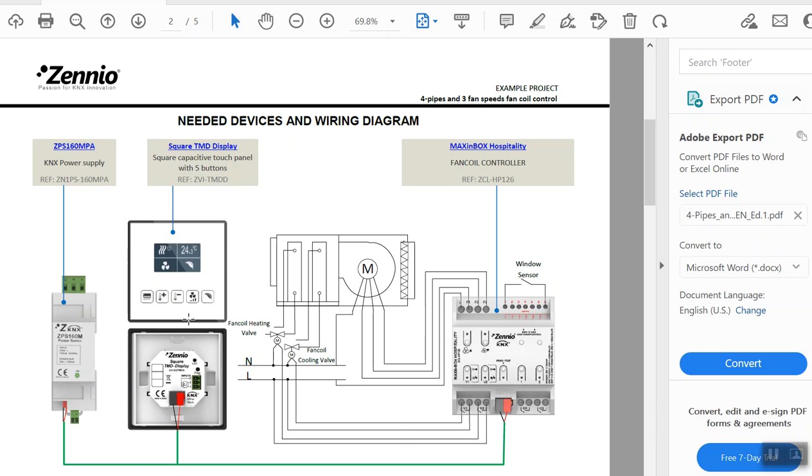In the thermostat you can see the pictures here. This is the on-off for air conditioning or fan coil. This is plus and minus to control the set point. This is the button to control the manual fan speed and change it to auto, because when you go to speed 1, 2, 3 manually, the thermostat goes into manual mode.